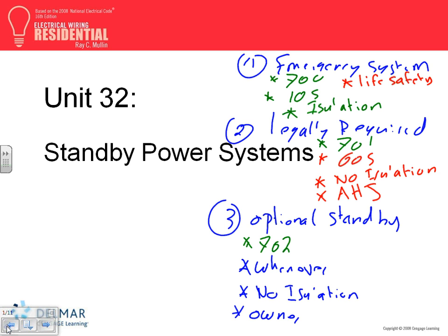Do we need to pick up, if we lose power, Brad, do I need to pick up every single outlet in your area? The outlets right in front of you guys. Do I need to pick them up? Are they an emergency system? No. Are they a legally required system? You're not doing very important things for the government or for the state or whatever. No. So what would they be then? Optional. I want to pick up the loads, optional.